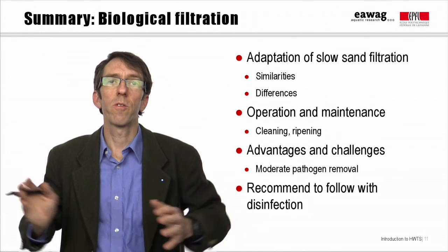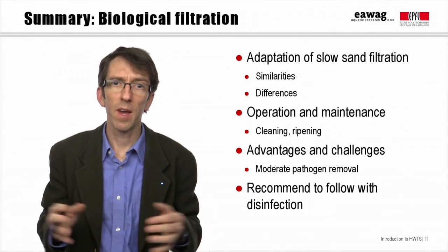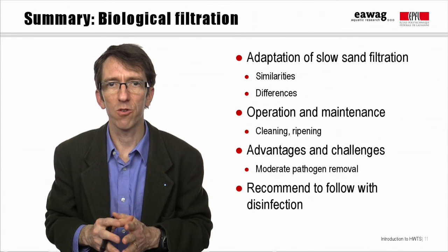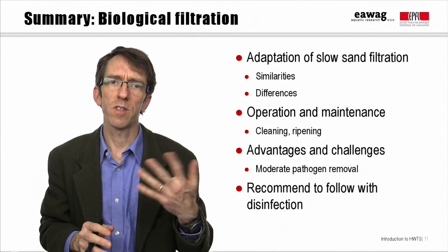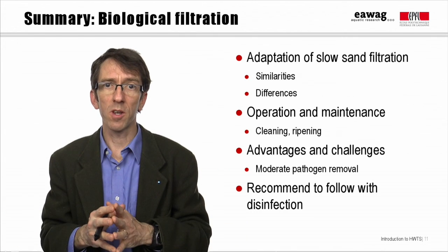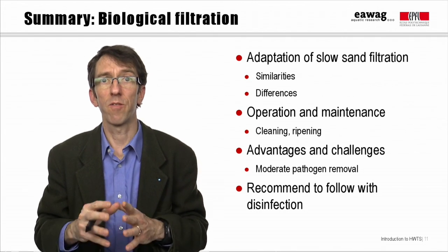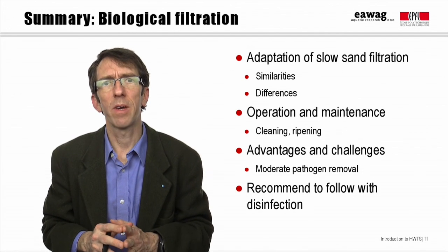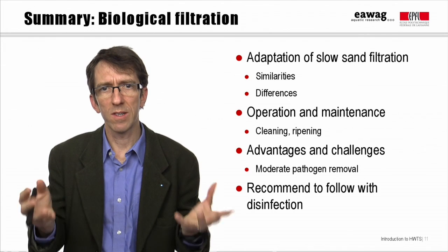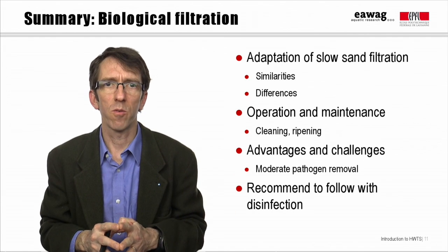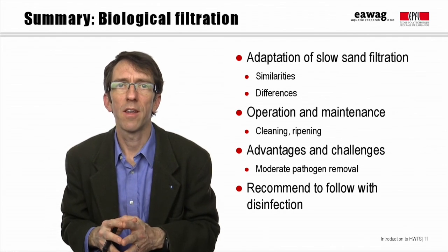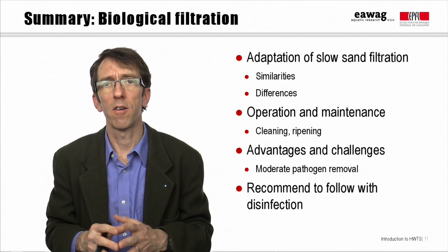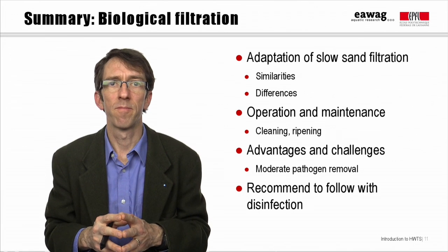So in summary, we've learned today about biosand filtration and how it's an adaptation of slow sand filtration for use at the household level. We've looked at some of the similarities and differences between biosand filtration and conventional slow sand filtration, and have gone over the operation and maintenance, including this important step of cleaning the filter when the flow gets too low and allowing some time for ripening to reestablish the efficiency of treatment.